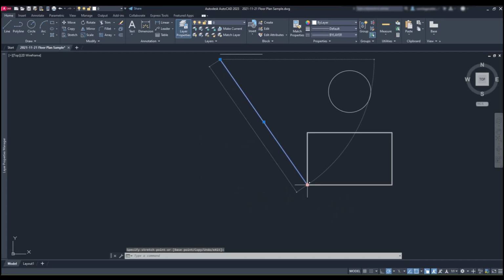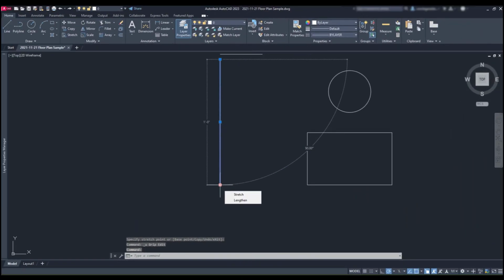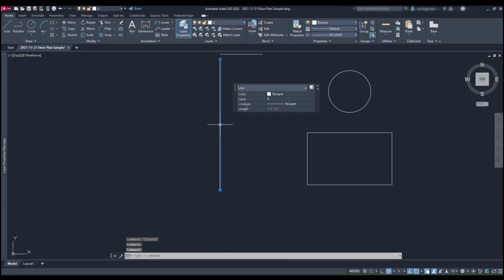This is important. Now, a useful and common thing to do here is changing the length of the line by moving the cursor along the track line. Now, if I type a value, I will add that to the total length. As before the line measures 1 foot, if I type ½ inch and press enter, you can see that if I double click on the line to see the quick properties, the total length is 1 foot and ½ inch.